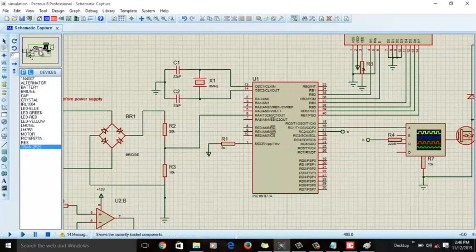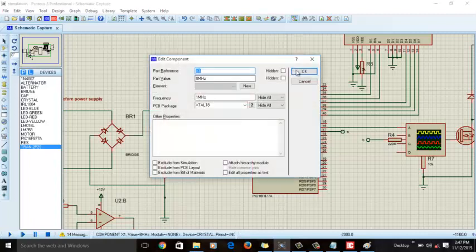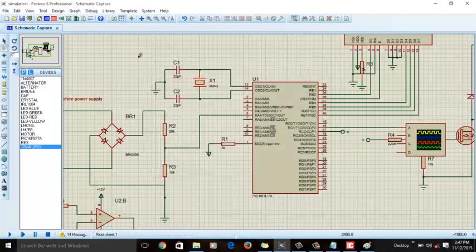Okay, so these are the components which we need to connect with the oscillator. Any computer or microprocessor definitely needs some kind of frequency to operate on. So this is the circuit on which the microcontroller will be operating. We are using an 8 megahertz crystal, so the microcontroller will perform instructions at 1 by 8 megahertz per second, which you can say becomes a microsecond.